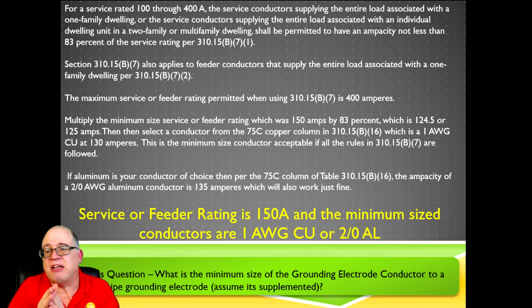So I'd have to do any adjustment and corrections from the 75. But the beautiful thing about the -2, whether it's on thermoplastic or thermoset being XHHW, for example, is that the -2 tells me I can use the 90 value ampacity-wise for adjustment and corrections, and that's important, all right? But we're in the 75 degree column, one, because typically that's what the terminals are going to be rated for. It's 60 or 75, either or.